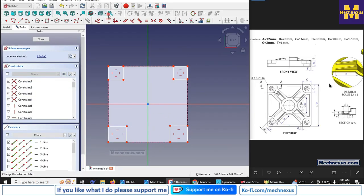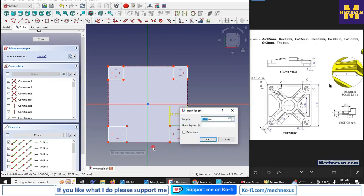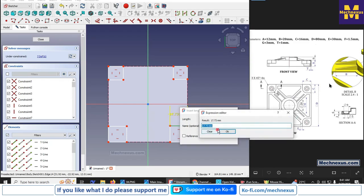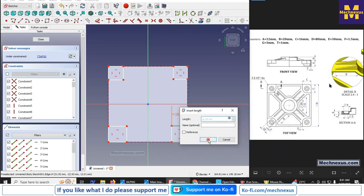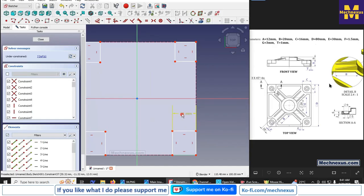And here I will select a smart dimension, and C is 16, so here I will go in expressions, type dd dot C underscore 16, say OK, and I will select this and make it equal.